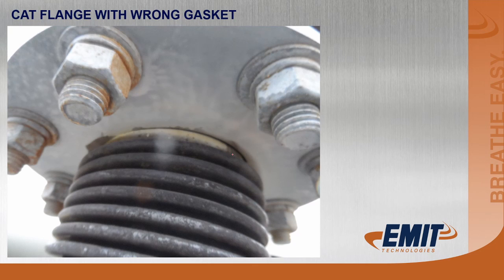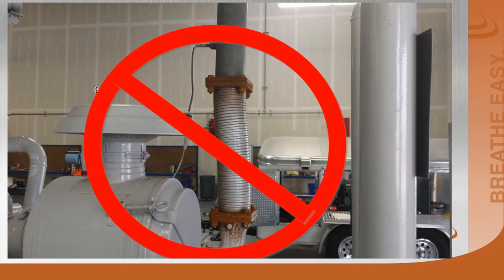Okay, this would be a CAT 3300 series flange with a Caterpillar bellows on it. And this flange is free to turn on this bellows. And if you use an ANSI flange gasket on here, that gasket is clear out here, and it doesn't seal against that flange on the other side. You have to use a Caterpillar gasket on Caterpillar flanges. Just a note.